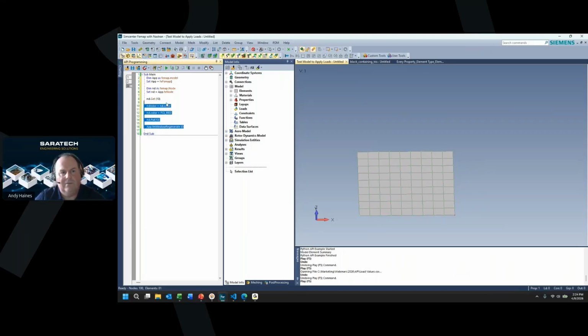All right, so that's all well and good, but let's say we wanted to actually pick a bunch of these things and do it at the same time. So what we're going to do here is use a set object instead. So I'm going to do dim nset as femap.set. I'm going to set nset equal to feSet. So now when I go to nset, again, these are all options. So I could just add one ID at a time, add them all by color, or basically every method that's available for selection is also available in the set object.